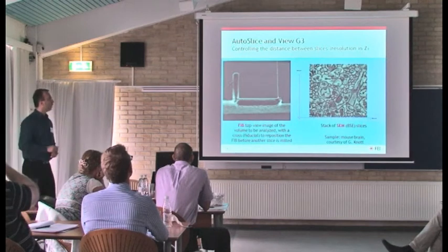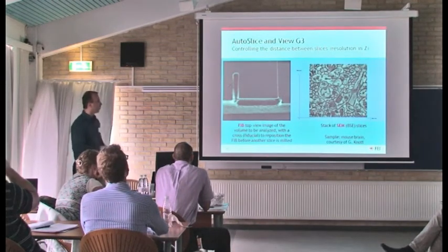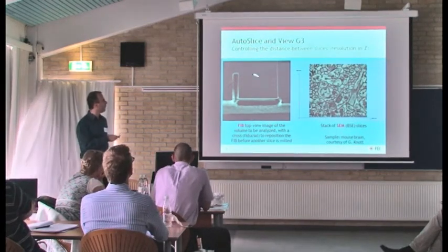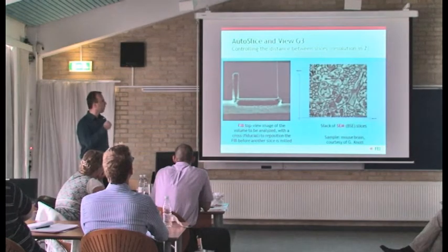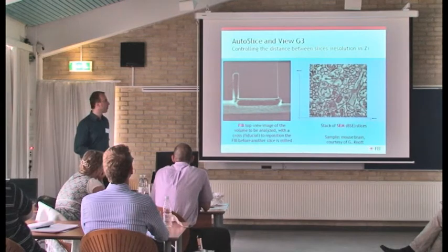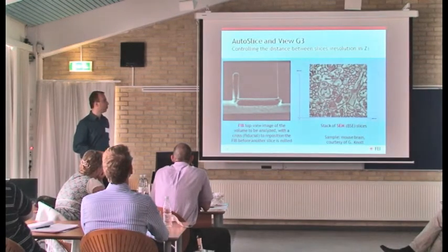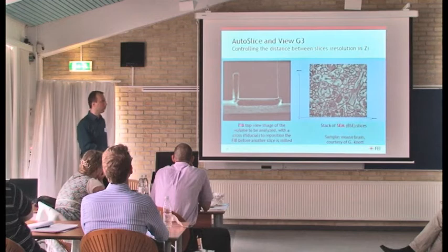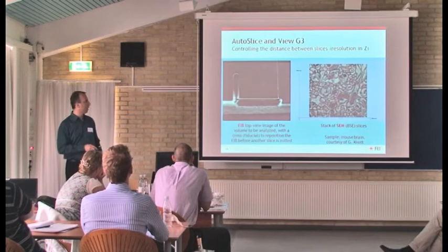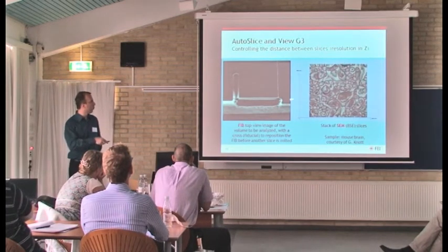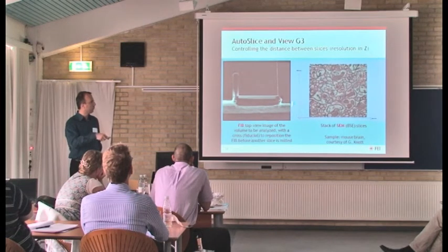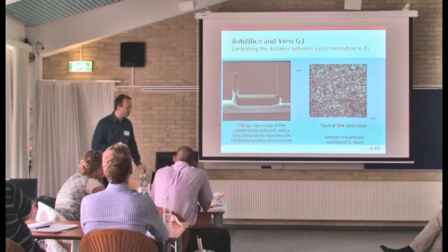So when it really comes to the Z resolution, some of what was done is pretty obvious. It's been about introducing fiducial marks so that one could accurately position the beam when cutting. This is an extra security, if you will. Do not assume that your beam is at the right place, but verify that it truly is there. And here we've got the complete acquisition top down with a fill, with every slice automatically repositioned and cut, and then the resulting SEM image.